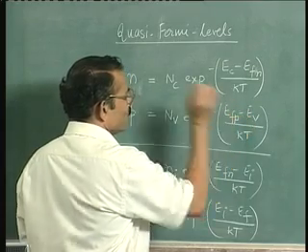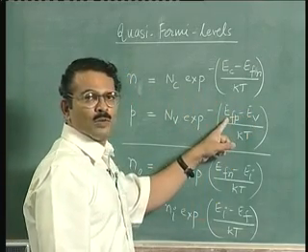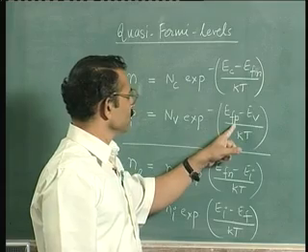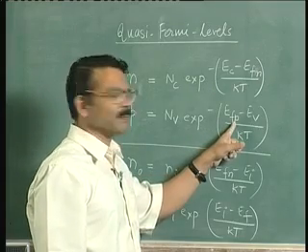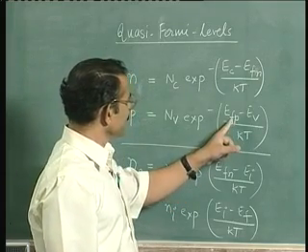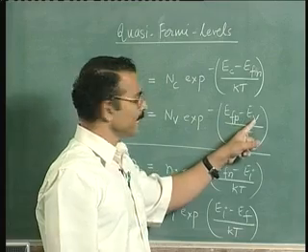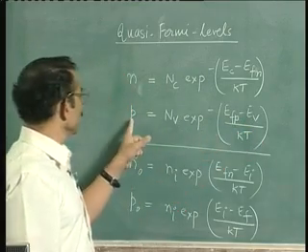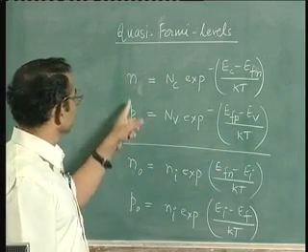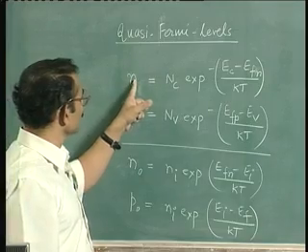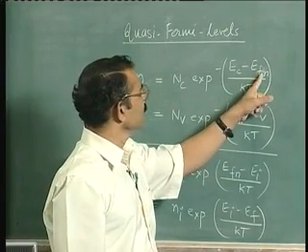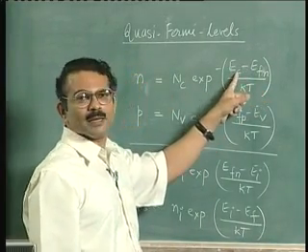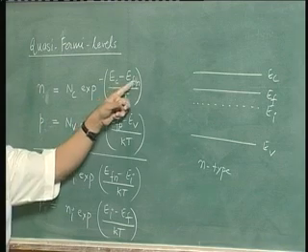So you have a new Fermi level for holes, which is different from the Fermi level under equilibrium. Now this means that the Fermi level should move closer to the valence band edge to have increased hole concentration. But in the same semiconductor, for increased electron concentration, your Fermi level should move closer to the conduction band to have the higher concentration, because this difference should decrease.